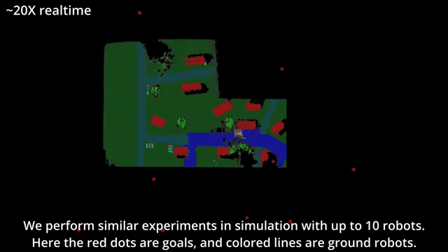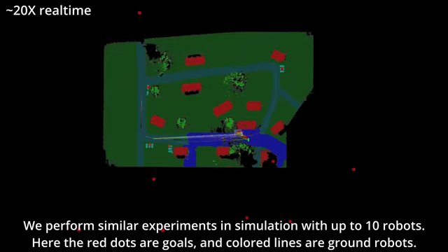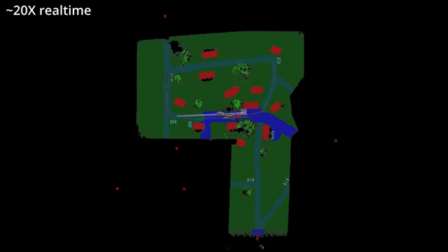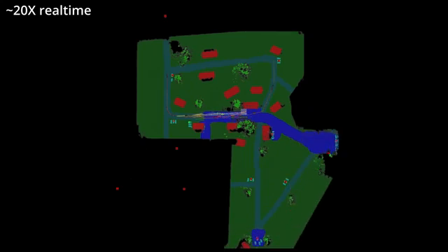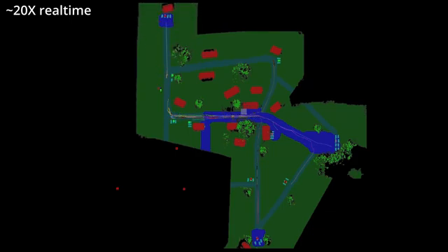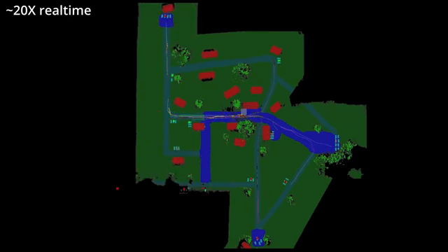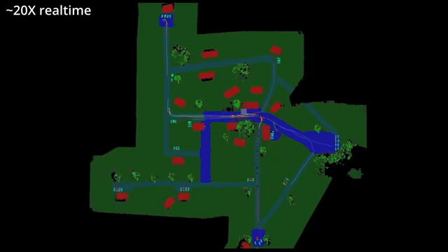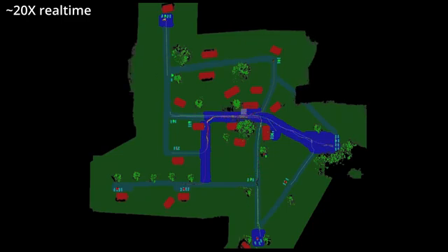We finally perform many experiments in simulation, such as the one shown here. In this experiment, 10 UGVs collaborate using our system to visit a number of different targets, all using a map constructed by a single UAV. We simulate limited communication ranges, so notice that the UGVs do not select goals until they have received maps. Once they do, they can be clearly seen collaborating and deconflicting objectives.